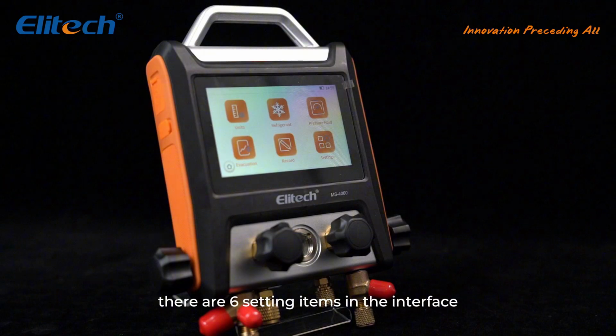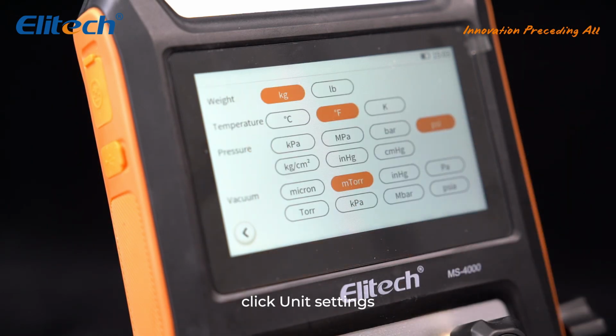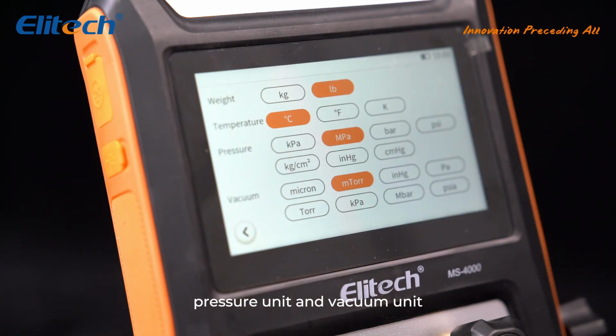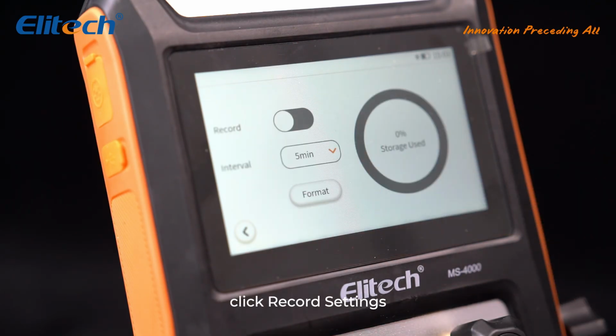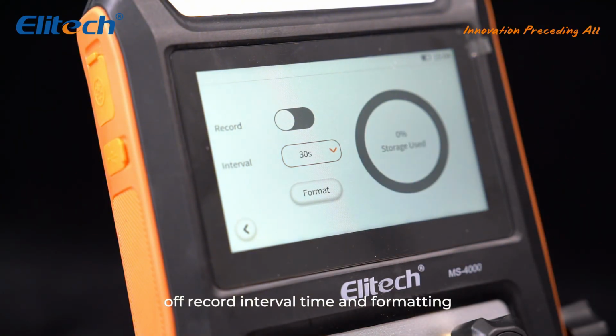There are 6 setting items in the interface: unit settings, refrigerant settings, pressure holding settings, vacuum settings, record settings, and system settings. Click unit settings, set the weight unit, temperature unit, pressure unit, and vacuum unit. Click record settings, set the record on/off, record interval time, and formatting.